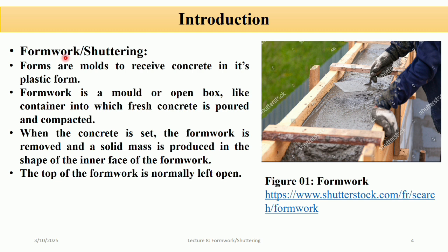So why do we provide the formwork? The purpose of formwork is that it helps to shape the concrete into the desired form and structure, and it provides support to the concrete until it gains sufficient strength to support itself. And formwork helps to achieve the desired surface finish and texture on the concrete. And formwork ensures that the concrete is poured and set accurately, reducing errors and defects, and it provides a safe working platform for workers to access and finish the concrete.